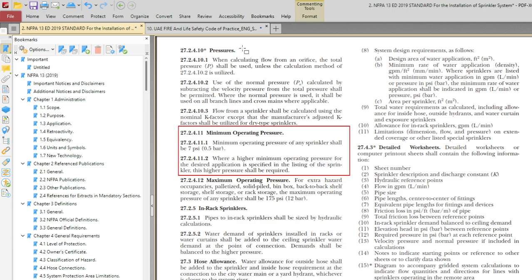Just now we calculated how many GPM? 225 GPM, right? Can you divide by the number of sprinklers? GPM divided by the number of sprinklers. Now we calculated 225, and 225 divided by 12 means 18.75. So that means approximately 19 per sprinkler.